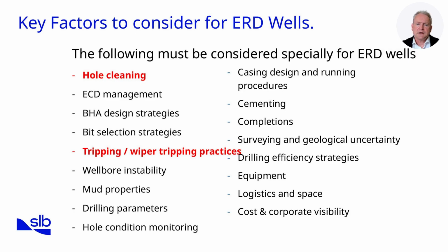Long intervals and high flow rates can drive ECD above fracture pressure, causing losses, or drop it below pore pressure, inducing influxes. Balancing hydraulics is essential. Next, BHA and bit design strategies must be optimized for long laterals. The assembly needs to be durable, minimize vibration, and provide steerability while keeping torque within limits.